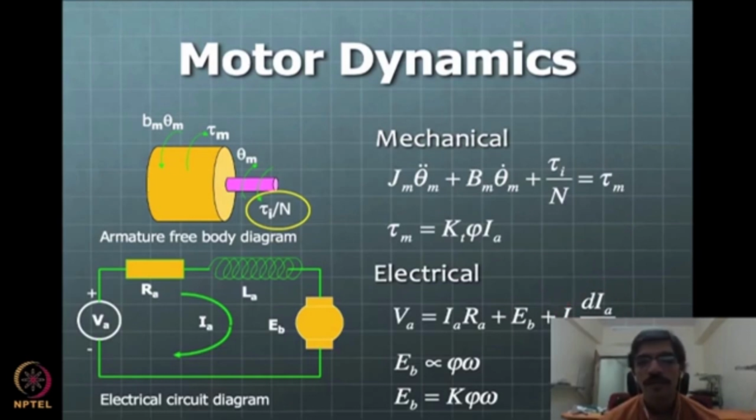So typically, L inductance of these motors is very, very low. So many times, for all practical purposes, this inductance is neglected. Okay, so this electrical dynamics, as I was saying before, is very fast dynamics. So that dynamics seldom affects the mechanical coupling effects. It doesn't matter really.